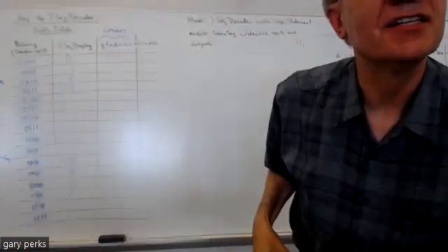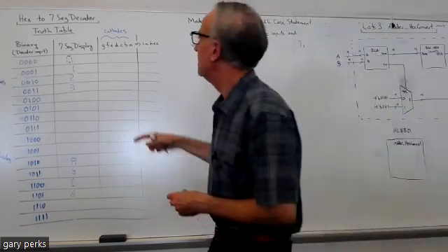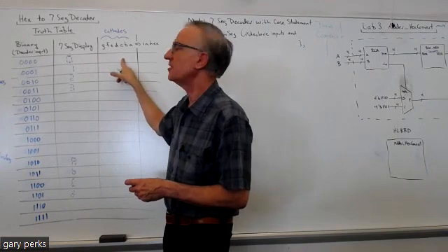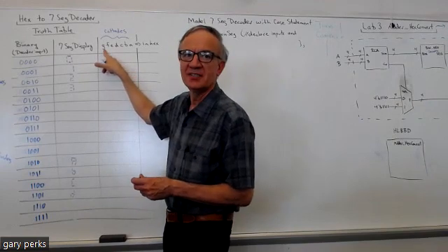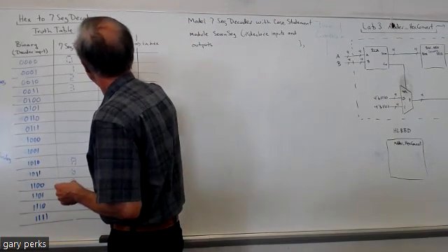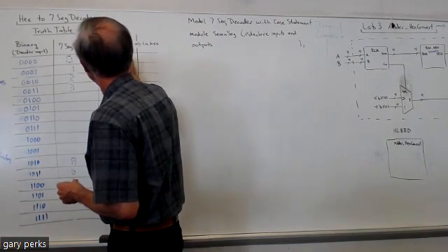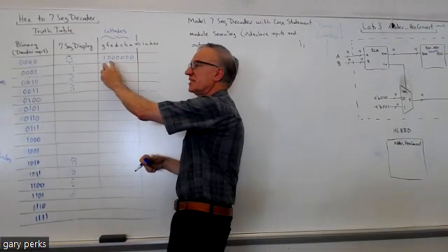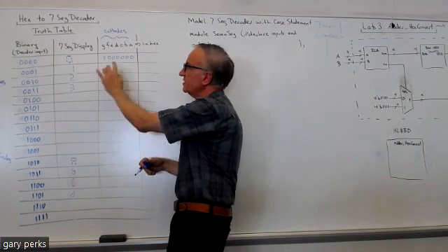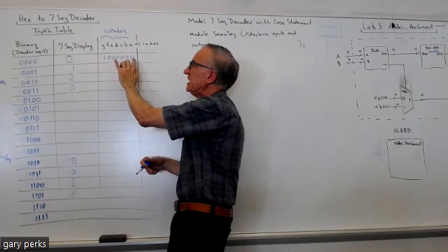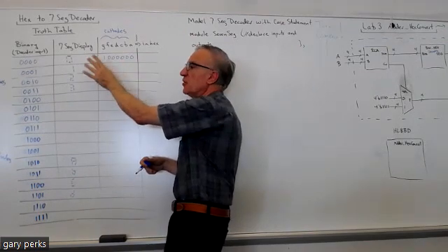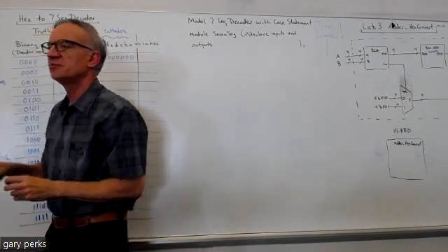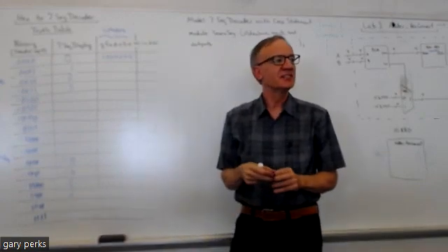What 7 bits would you put here to get a 0 to light up? Which ones? Say. So these 6, you would want what value? 0. And then what would you do with G? Yeah, make it a 1. So it'd be 1, 0, 0, 0, 0, 0, 0. We made these 6 cathodes 0 because that's going to light the segment, right? The segments we want lit, we make the cathode 0. The segment we don't want lit, we make a 1. So the only one we make a 1 is G, because that's the one we don't want to light up. We want to light up all the other 6.